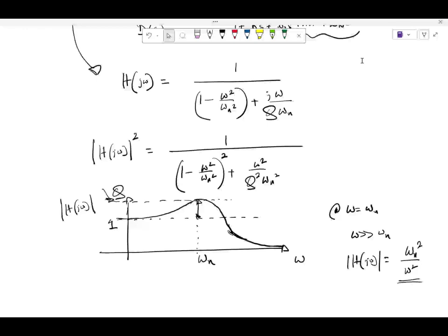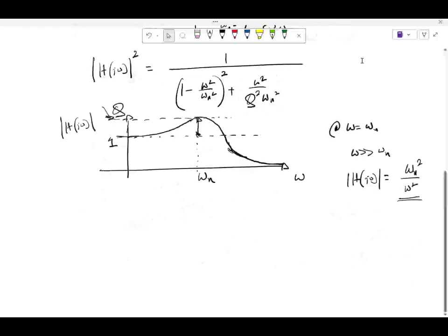Okay. So now let's come back. I will not concern myself with higher order transfer functions, more than 2, at this moment. But we have to continue the discussion we started, because we wanted to convert everything to a first order system and see when we can and we cannot. So now, if you have a first order transfer function, which will be of this form, let's say 1 by 1 plus S over P.